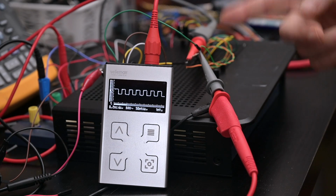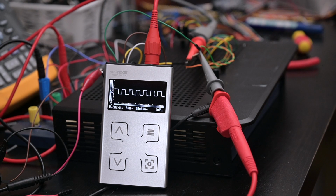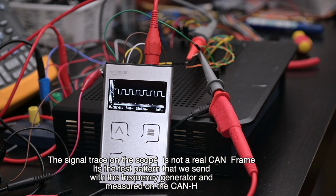I'm just checking on one of the wires, CAN high I believe this is, and you can see it shows the trace pretty nice. Of course you cannot measure between the two, CAN high and CAN low, but you can measure one at a time, and then you can already make a decision if the CAN bus is in a short or not. So the question now is, can you really troubleshoot the electrical levels with a voltmeter?